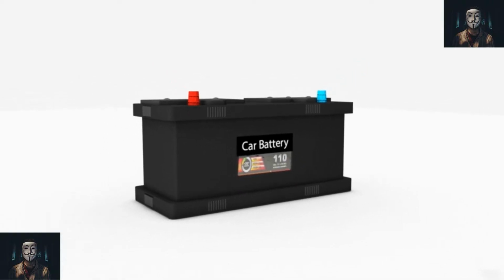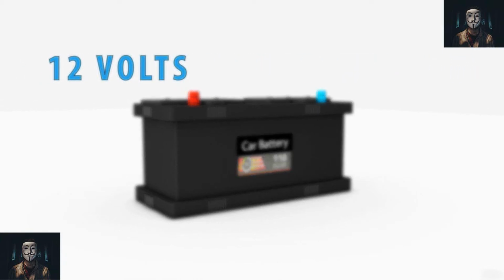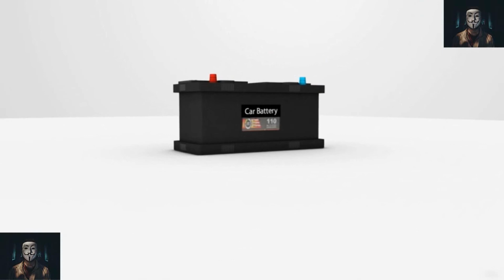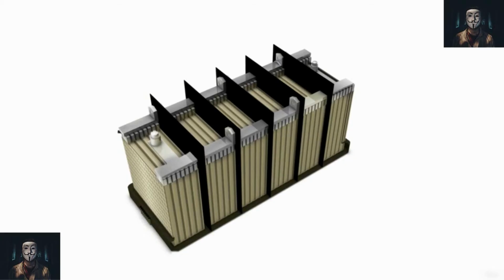Battery charging can be described as slow or fast. Slow charging is best, but in an emergency a fast charge is acceptable. When recharging, a battery should ideally be disconnected from the vehicle electrical systems. There are two types of battery charger: a bench charger, which has a current output of up to 10 amperes, and the fast charger, which can recharge a battery in 30 minutes with a current of up to 50 amps.